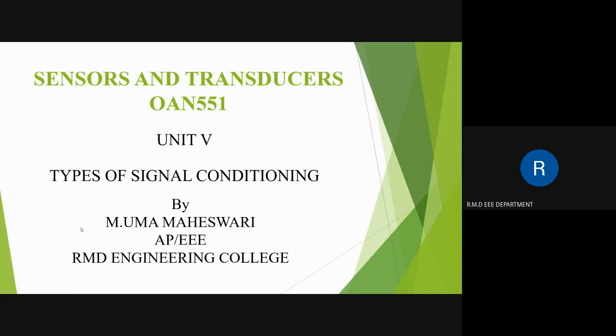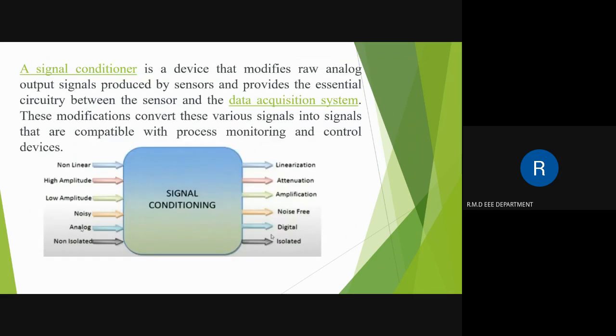So now we have understood what is signal conditioning. It is used to process or modify the output signals from the transducer into a form which is usable by the necessary applications. Now, the necessity of signal conditioning. The signals which are reaching the transducers may be too noisy due to electromagnetic interference. The signals may be too small, usually in the millivolt range, so we have to amplify them, changing from low amplitude to high amplification value.